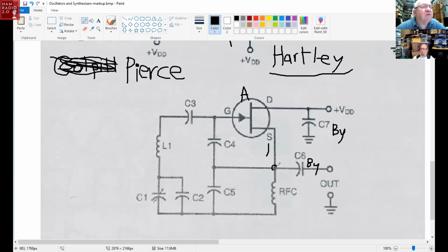And again, here you cross the wires at right angles. And this is intended to be a junction, not the wires not touching, which is bad schematic drawing practice. But this must be an old diagram before that became a pretty good convention. So I always draw schematics: if the wires are going to connect, they connect at right angles. If they cross like this, they're not connected, although I'll usually draw my schematics with the loop over, so it reminds me that they're not connected and it's not ambiguous in case the dot is really tiny and about the same size as the line.